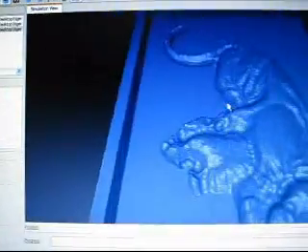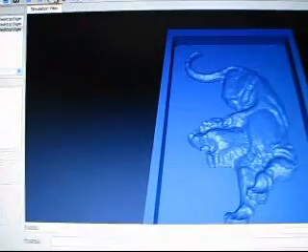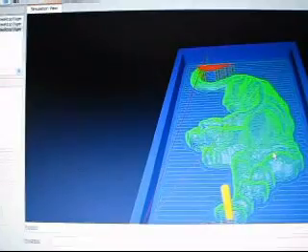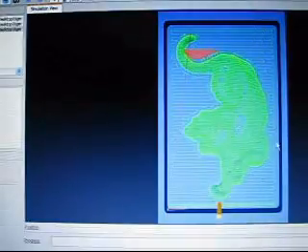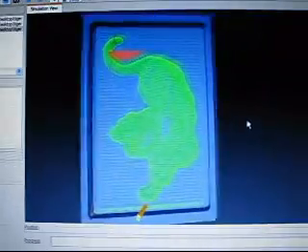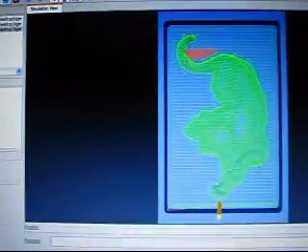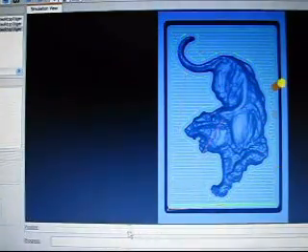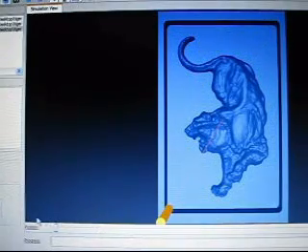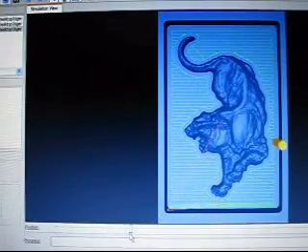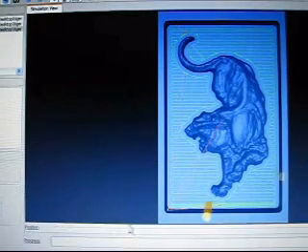Alright, now what's interesting about this program is, let me turn the tool path back on, and I'll turn the tool back on so you can see how the tool changes as well. If I back this up on this slider on the bottom, I could take this all away and just, here's our roughing, notice the size of the tool, it's a 1/4 inch tool, okay, and then it changes tools right around there.